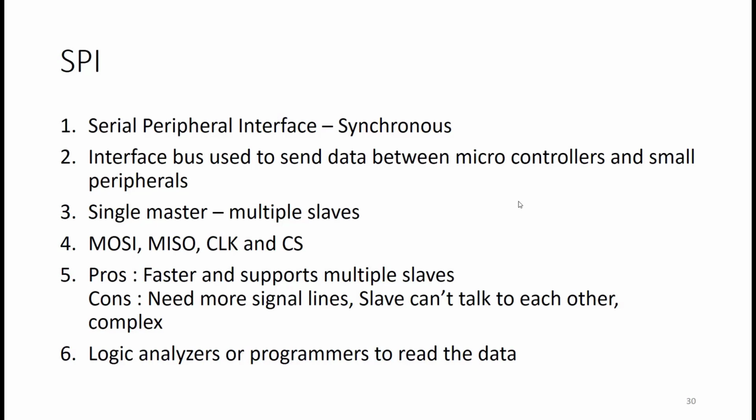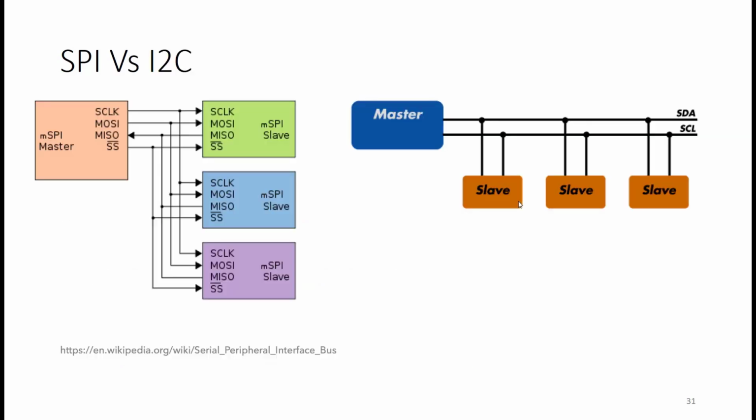To understand the SPI communication, again, logic analyzers are the best option to read the data. Apart from logic analyzers, there are programmers specially for SPI through which you can read the SPI data. So here is a comparison between SPI and I2C.